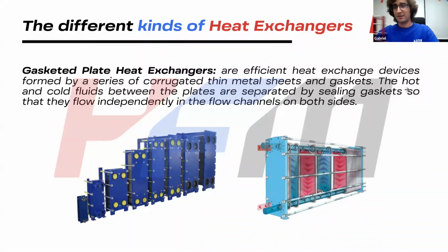And you see that these plates are exactly this part. These are the plates that are inside between these frames of the heat exchanger. And this is how they are attached together. The gaskets are attached to the plates in order to avoid the fluid getting out of the plate itself, because it needs to be sealed. And that's the function of the gaskets when they are added to the system.